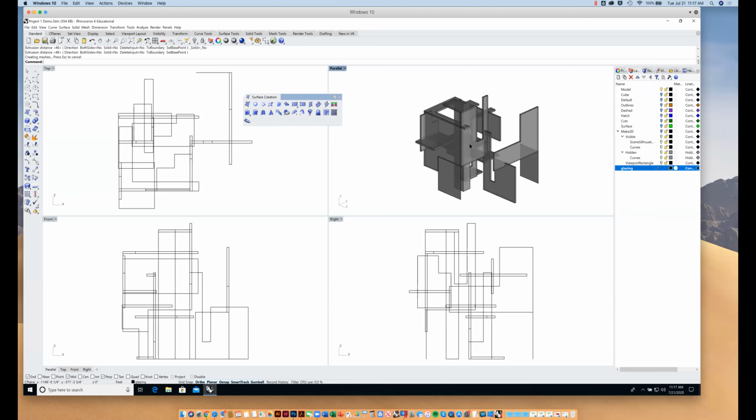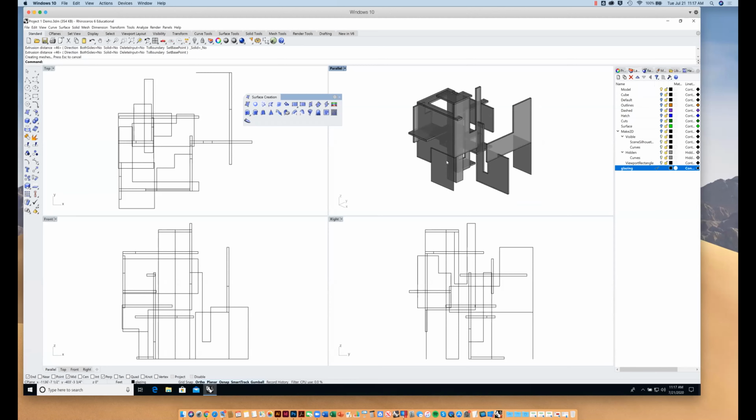All right. And so, whereas Rhino is really handy, it's really easy to make all kinds of weird geometries and shapes, right? And model those really quickly, like we were just doing. In Revit, it's harder to make a non-standard wall. You almost have to trick it into doing that. But what it can do is we can bring this geometry in that we've already created, start to make it walls, start to give it some materials, and then start to make all that geometry like I was talking about. So it's about detailing in Revit for this class. So we're going to use each software's strengths and talk about how they're complementary to each other.